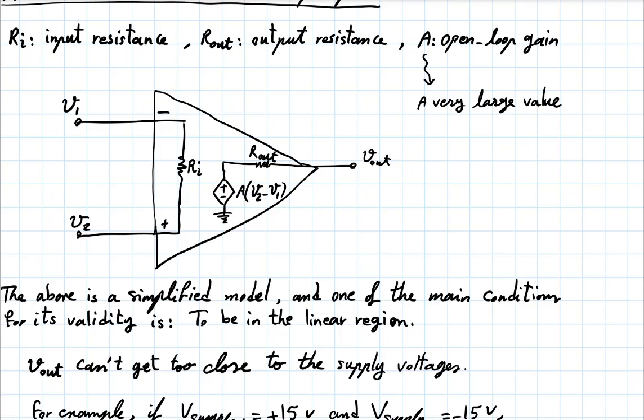So if you have a small voltage difference somewhere, let's say something that you have picked up with an antenna, and now you want to connect this op-amp to the nodes where you have that voltage difference, well, you don't want this op-amp to influence that voltage difference, right?